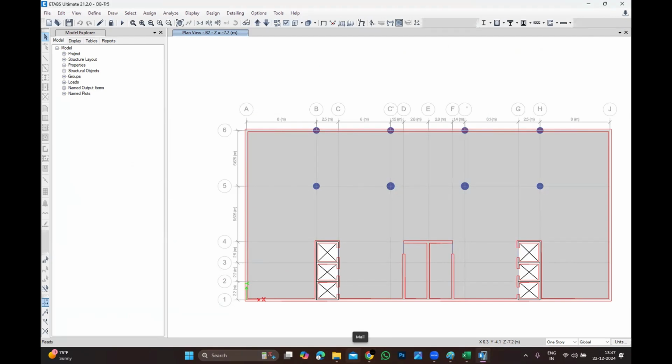When you have a building like in Business Bay, a slender building, width कम रहेगा, length ज़्यादा रहेगा, then there is a lack of stiffness. Problem क्या है? Stiffness and weight. It requires mass. If you do have sufficient mass, it is okay. If you don't have it, definitely you will have a problem.